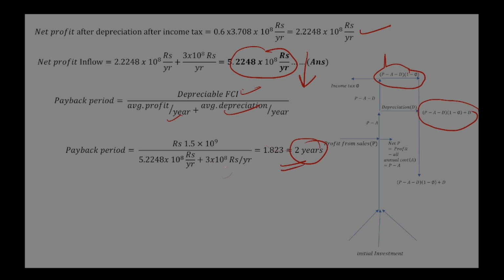So this is the thing. Hope you understand. If you have any kind of confusion, you can comment. Okay, so the response of a thermocouple can be modeled as a first order process to a change in the temperature of the environment. The thermocouple is at 25 degrees Celsius and is suddenly immersed in a fluid at 80 degrees Celsius. So initially the thermometer is at 25 degrees Celsius and we are immersing it in an atmosphere of 80 degrees Celsius. So xs is equal to ys.